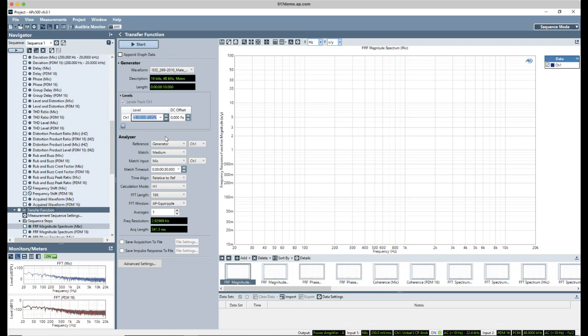So I'll just quickly say here that 114 dBSPL set in the signal generator will get me what I expect for this speech signal. I think we have a blog post up on our website that talks about how to find the crest factor and set a generator level depending on the non-sinusoidal signal you're generating. But for this moment, we'll just set this at 114.